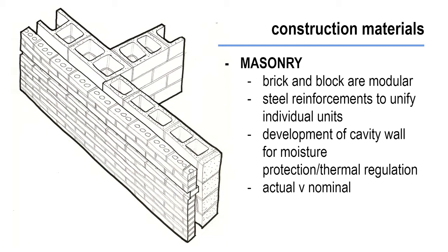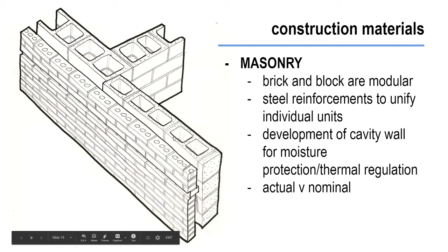used a lot in masonry jobs as they provide an empty space between materials where water can drain instead of storing all the water inside, which prevents mold from forming and water from freezing, because as I said, is a typically bad thing. And so here is kind of a 3D section of sorts of a cavity wall.